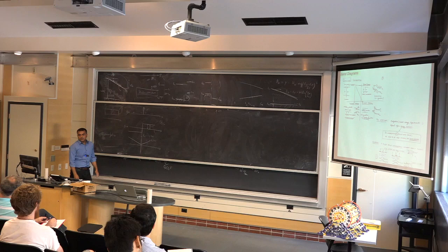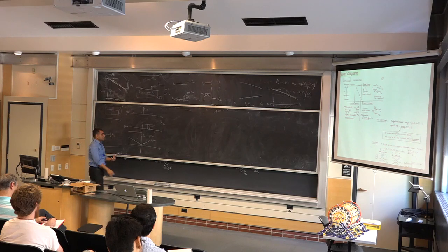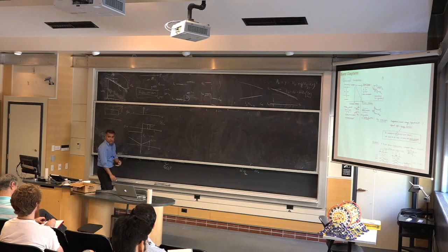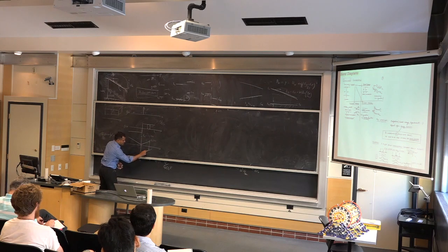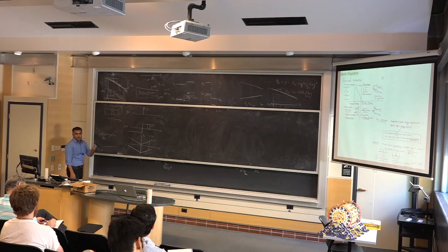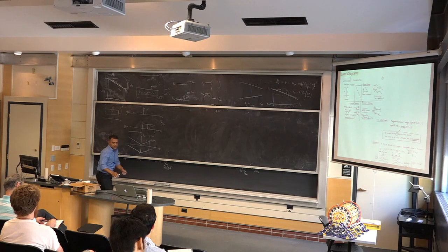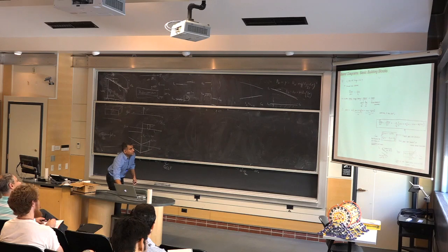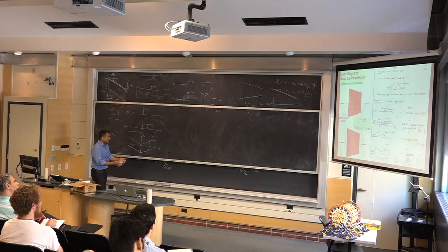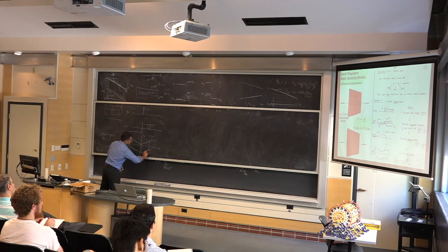Where's the valence band? The valence band is always the band gap below the conduction band. That's Eg. That's not changing, so the valence band is going to do that. That's the energy band diagram if I have a positive charge inserted somewhere down here. This is the band diagram. Valence band, conduction band.